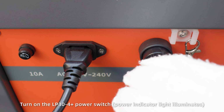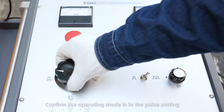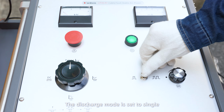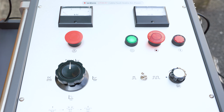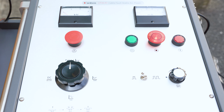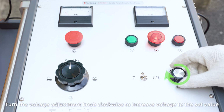Turn on the LP30-4 Plus power switch. Power indicator light illuminates. Confirm the operating mode is in the pulse setting. The discharge mode is set to single. Press the power button and press the high voltage button. Turn the voltage adjustment knob clockwise to increase voltage to the set value.